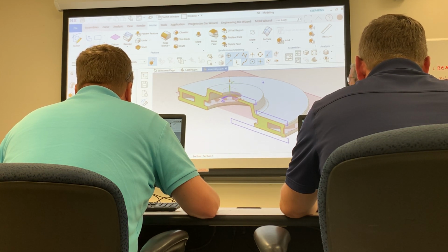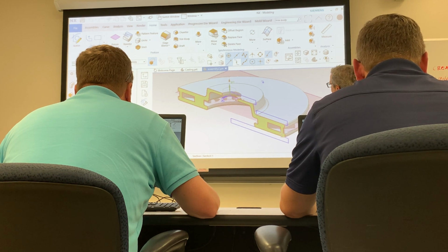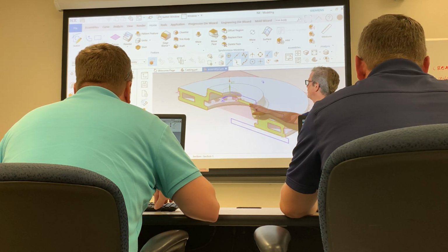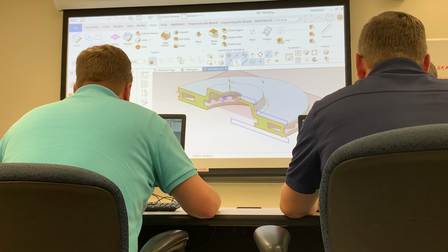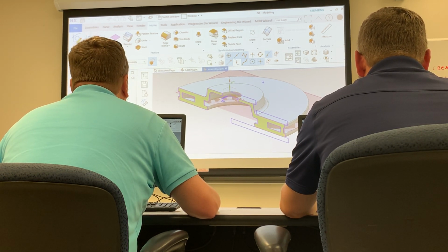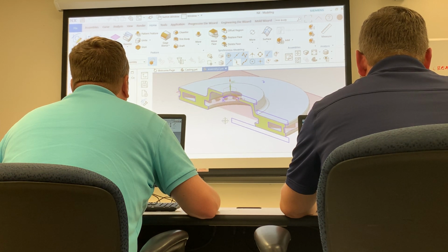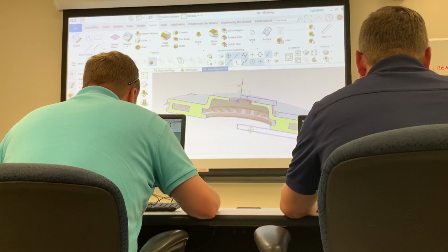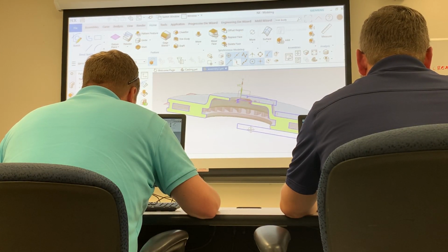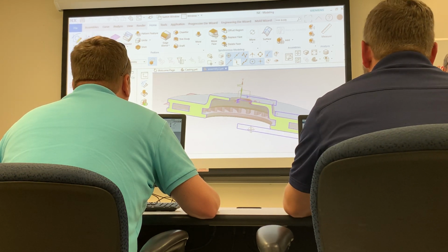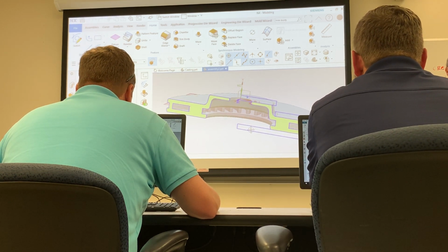But what really matters, what's critical in this case, is distance down, distance up. That makes the width of this critical, and then the distance from this outer face to the top face. Those are what's critical, so those need to be dead on. In fact, the geometry of everybody's models will all wind up being identical to each other, in terms of the solid. Your sketches may have all kinds of variation in them, but what gets produced will be identical.